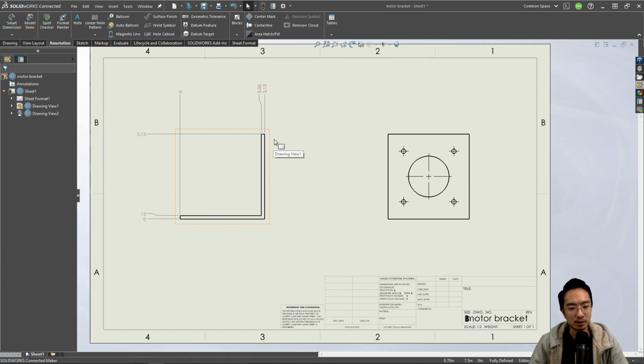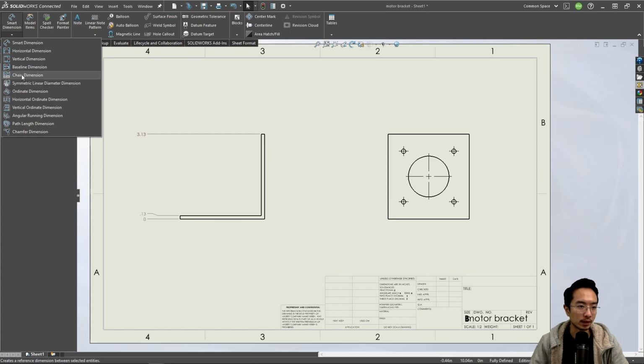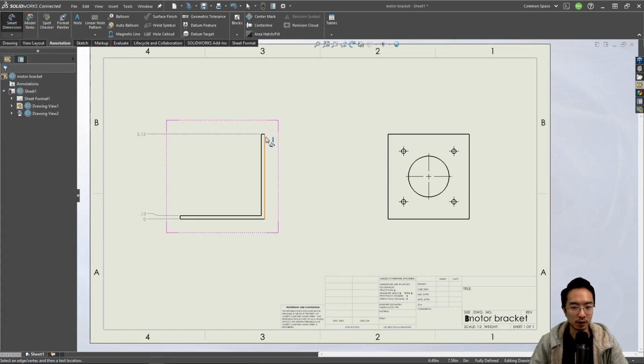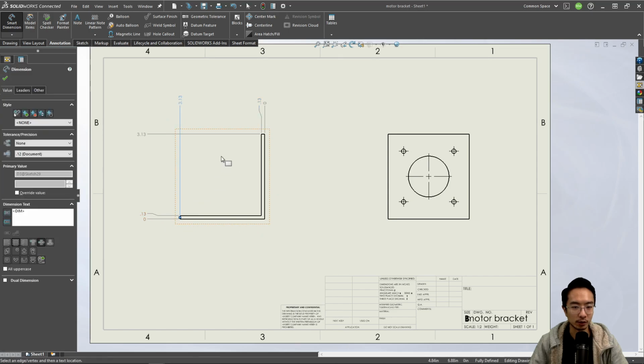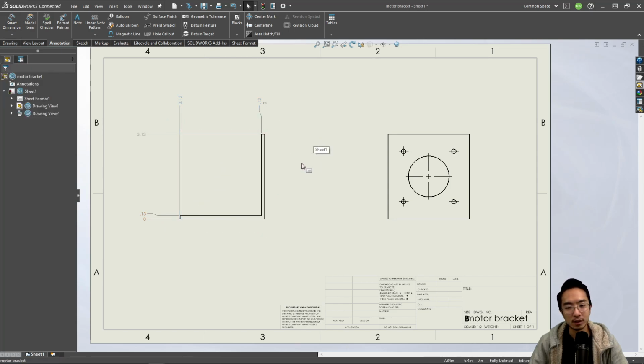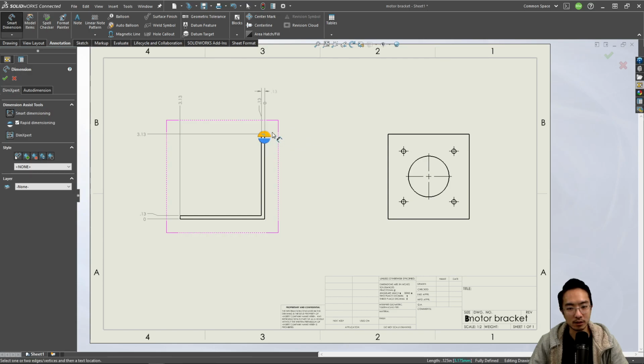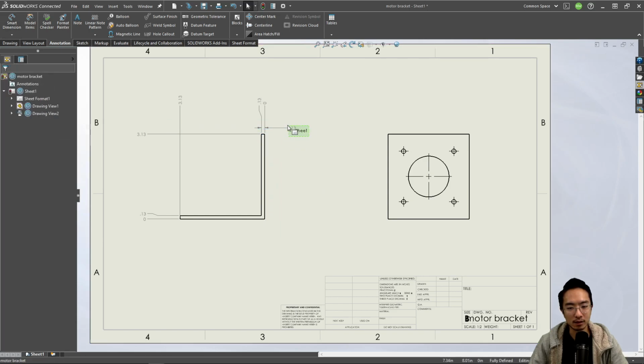So you can see that this fully defines the sketch. And sometimes maybe you would start the 0 on the other end if it makes more sense to you. That way you can see the thickness more easily. So that's kind of a preference, thinking about where the 0 is located for the person. And sometimes you might see a smart dimension come in here and say the thickness. But in this case, that would be duplicate. So really, this should suffice to fully define this.